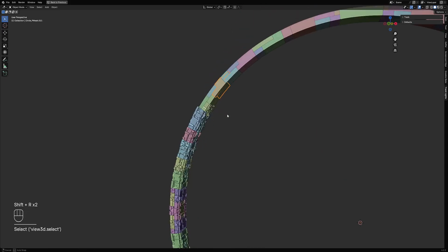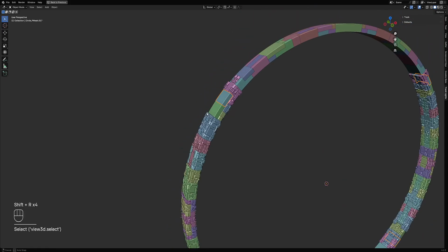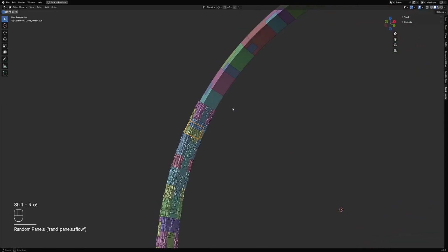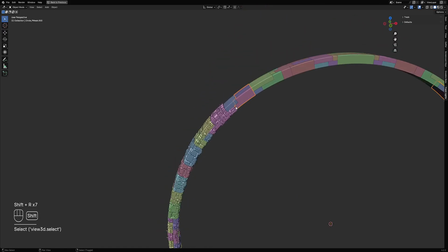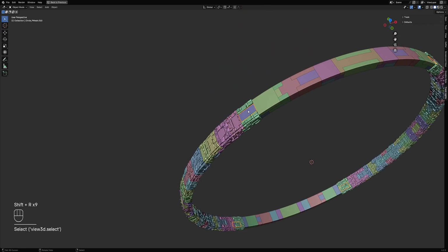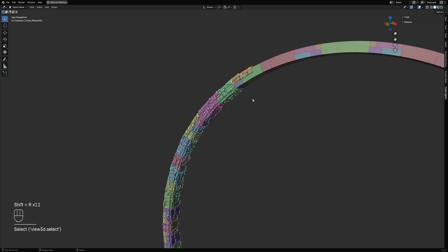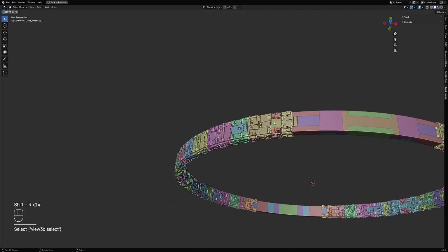The source mesh underneath is still intact. You can choose to merge that using the partition mesh operator or not. But in this case, we can just leave it separated.